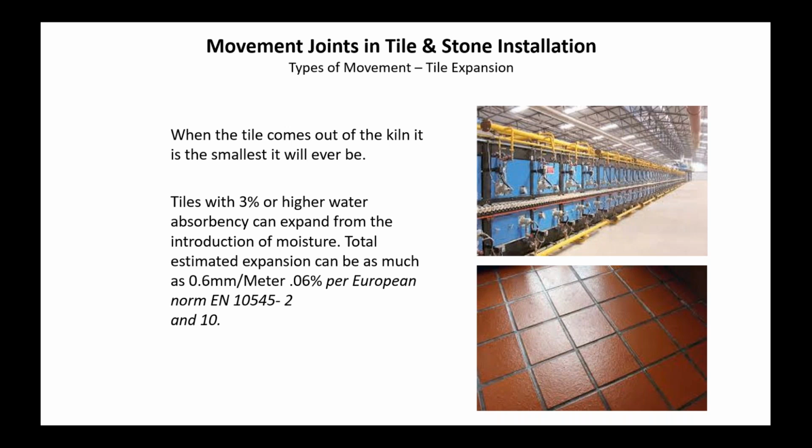So that's a lot. When you walk into a fast food store and you see that the toe of the cove base is pushed back into the drywall and the top of the cove base is pushed away from the wall, it's actually stress from the floor that's causing that. Again, this is what causes quarry tile pop-up in commercial kitchens. Movement joints are essential. Either you place them or Mother Nature will. You might hear me say that a few times because I can't stress it enough.